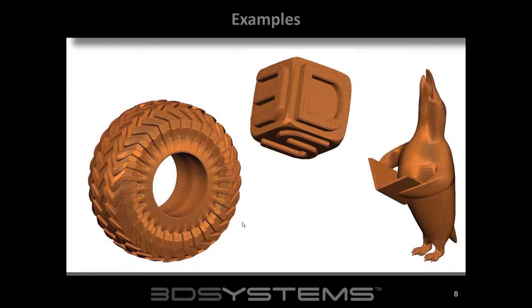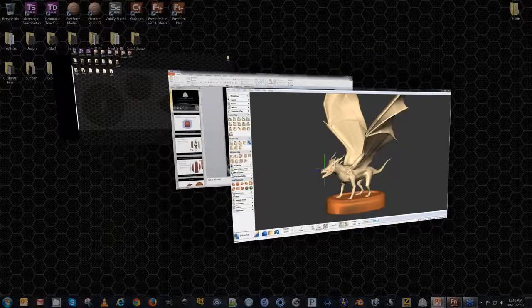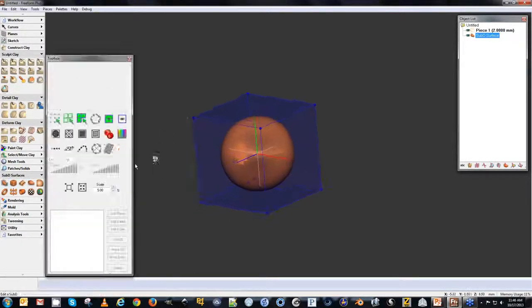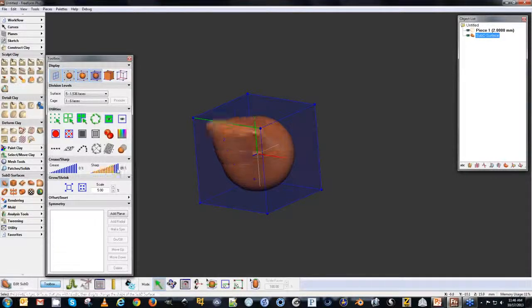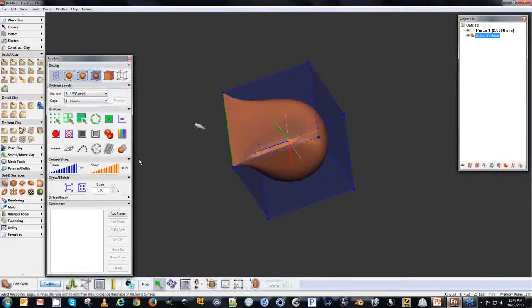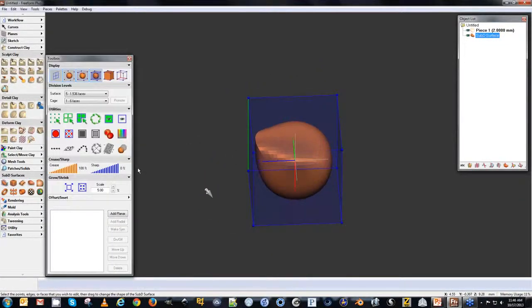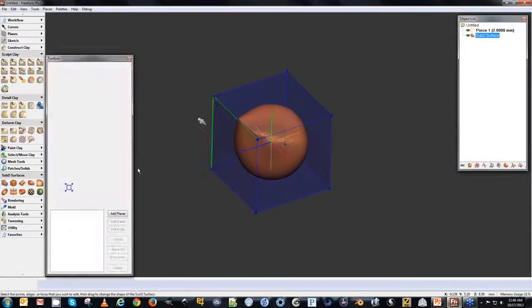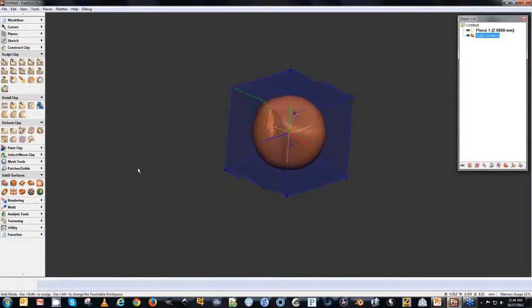So if I go back over here into Freeform really quick, and go to this model right here, rotate around, if I select this edge and I sharpen it, you can see that it is pulling every single face to fully meet the edge of the cage. Creasing is going to influence the model, so it's going to sharpen along that edge, but it's still going to try to keep some of the contour and smoothing that is defined by the algorithm.